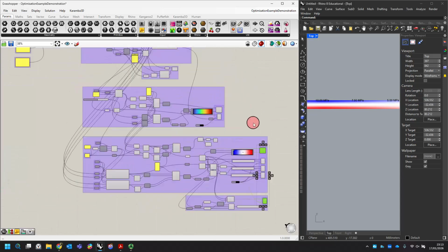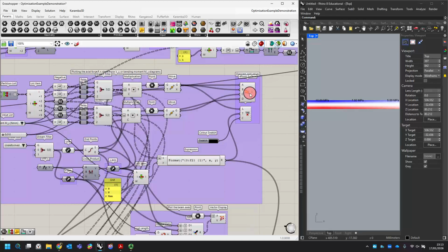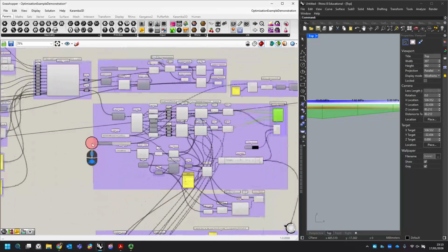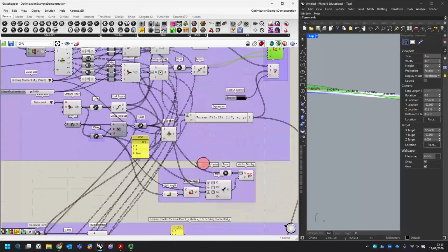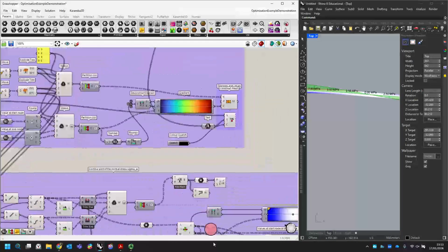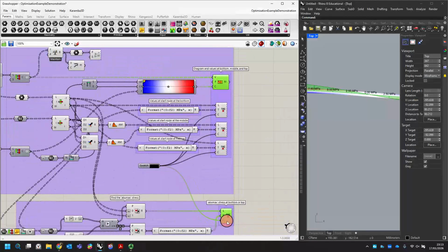So I'll just try and leave this on, and maybe actually we'll also show the bending moment diagram. And then the last thing that I'll do is I will change this to a deformed plot. So maybe I'll just turn off the numbers for a second. So just Control to turn them off.